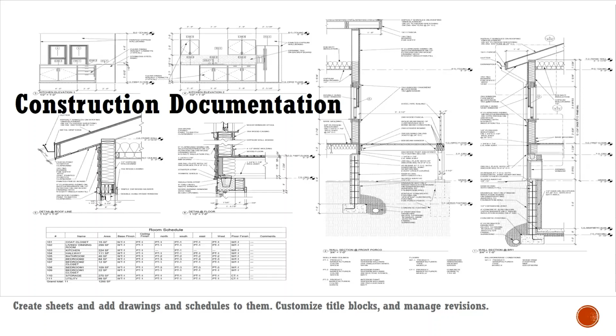Okay. Next comes the important part, because after the designs, it is mandatory that we prepare our construction documentation. Since I said we'll be inputting all the information to the components in Revit or in the BIM platform, it is very easy to develop our construction documentation also. Schedules, quantities and estimates, we can create with 2 or 3 clicks. Once you develop the model, it's very easy to create that. I'll be getting the estimate.